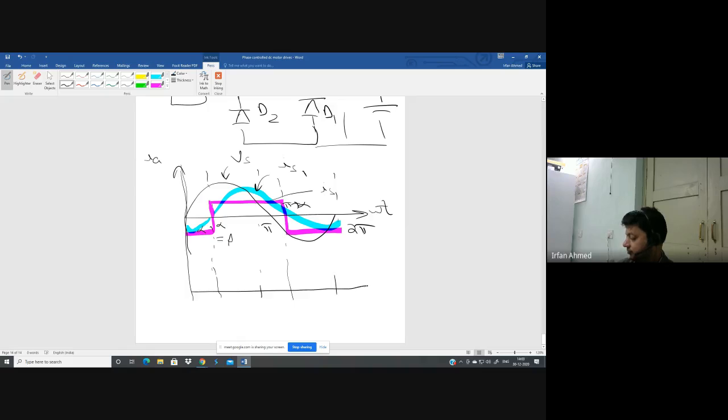Whereas if we go for the half converter or semi converter, we are turning on T1, T2 here. So your supply current is equal to the output current. Here freewheeling starts, so your supply current is 0. Here we are turning on T2, so supply current becomes equal to the negative of output current. And here again freewheeling starts. Is this clear?